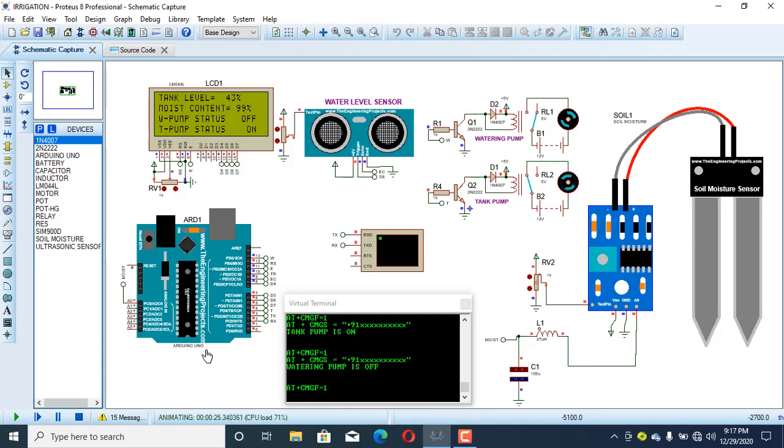So at those hours we are going to measure the content of the soil, because the reality is, if the soil moisture is measured maybe at 14:00, of course the soil may be dry, right? And the soil moisture sensor will detect that, and we are going to water the plants. So it would be illogical, because we are going to kill those plants if we water them right at noon, right? So we are going to use the RTC module to operate our system, maybe from 8 a.m. to 9 a.m. and then choose other working hours, maybe from 17:00 to 18:00.